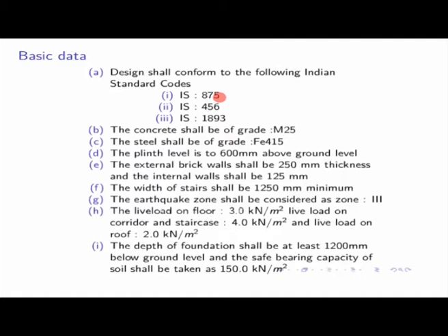So obviously for that case you have to consider differently; in a normal situation it is 4 kilonewton per square meter. Take a lecture hall complex with a staircase: when students are going in class it is thin, but after the class all the people are just jumping and coming out of the class and using the staircase. Considering that aspect, we consider 5 kilonewton per square meter.